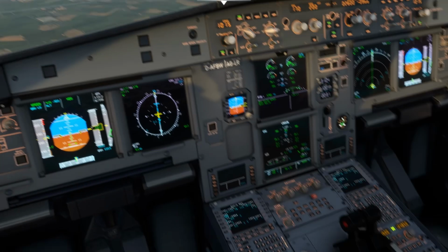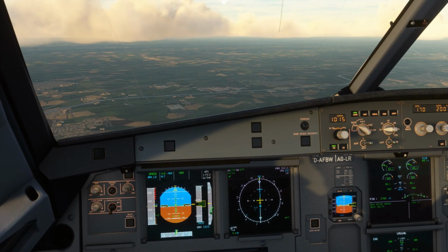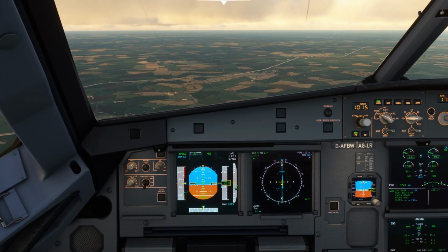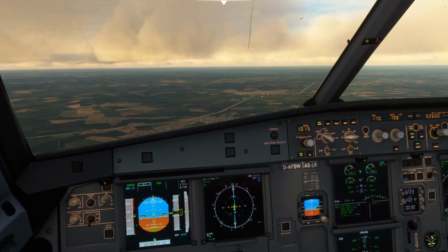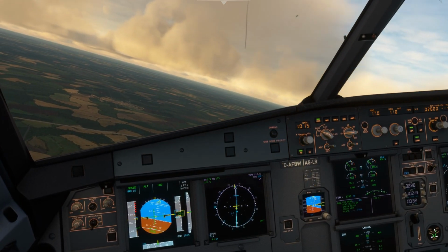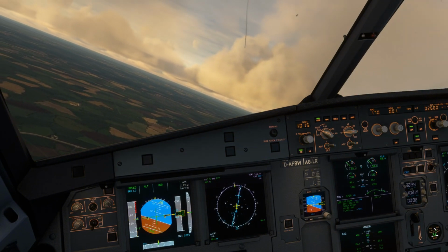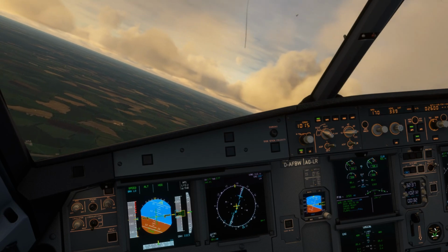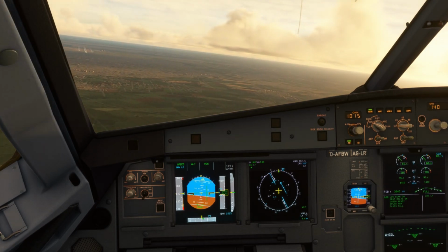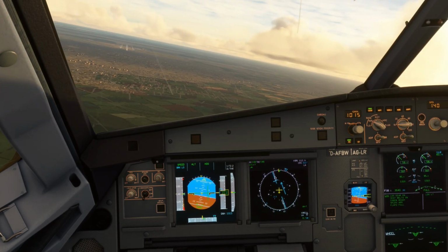Speed 170, speed check, flaps 3. After rolling out on the final approach course, that is 353. Approaching 9.5 nautical miles and 2600 feet, starting turn left and heading 353. Visual with airfield. Runway 36 right identified.